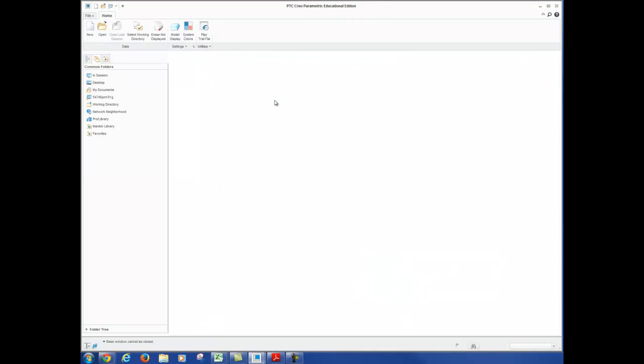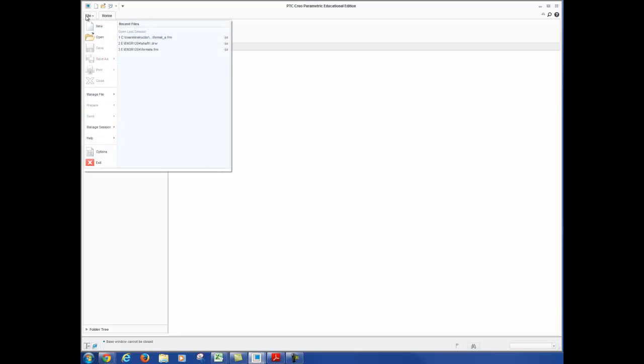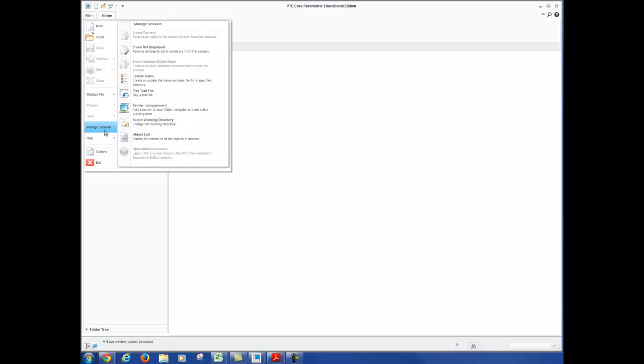After you've closed it, what we need to know is that Creo keeps a working history of all the drawings and parts while it's open. So each time you open Creo, it creates what is called a session history. In order to erase the history of the drawing or part from a session, go ahead and click File, go to Manage Sessions, and erase all objects not displayed.